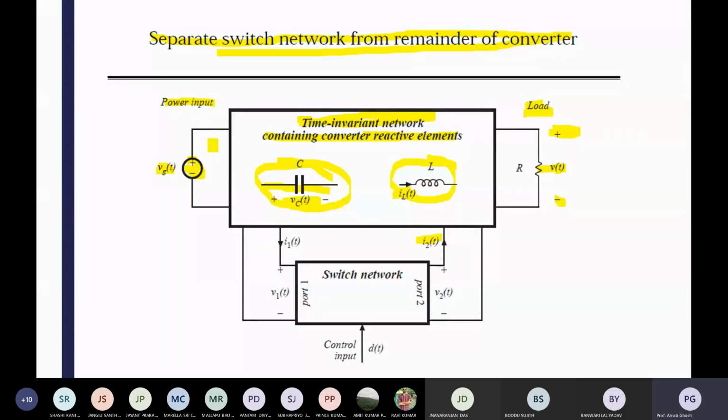In a solar panel you can also do testing, like an open circuit test, or no load test, to see how much maximum voltage may be developed by the panel with maximum irradiation or temperature. And how much maximum current will be developed if there is a short-circuited path, meaning you are shorting the solar panel output. Then you calculate the maximum current.